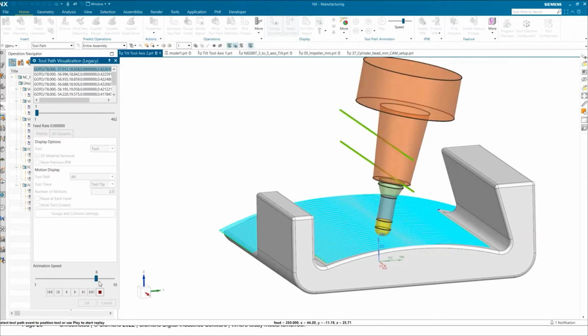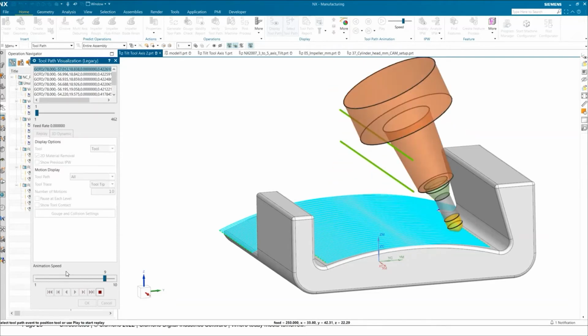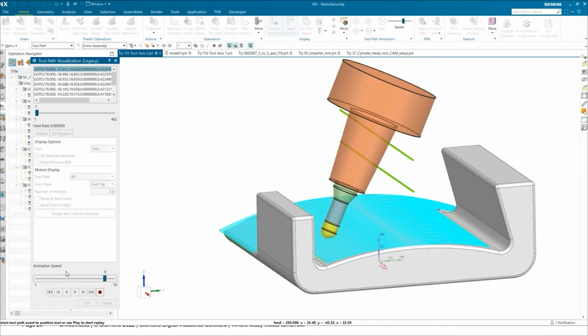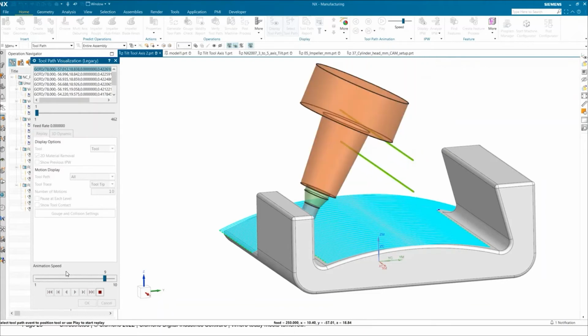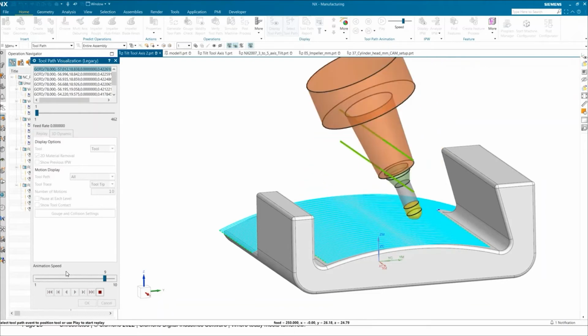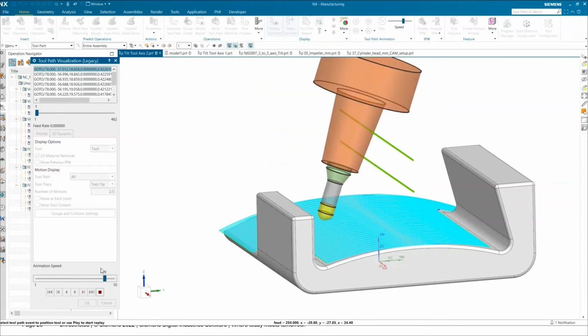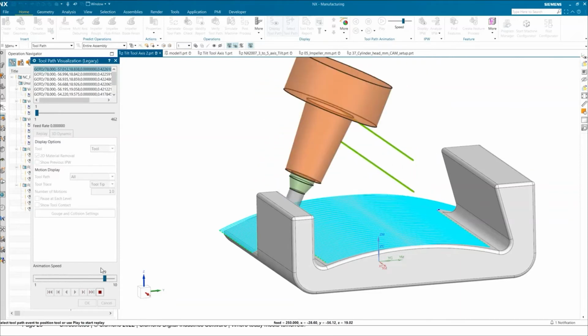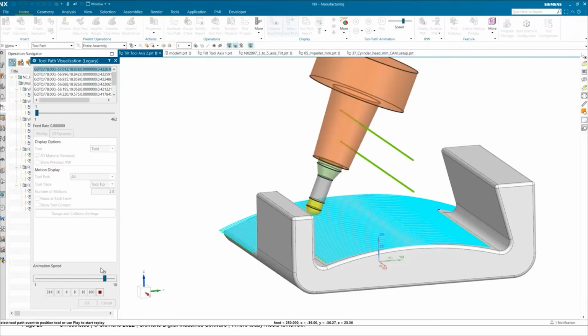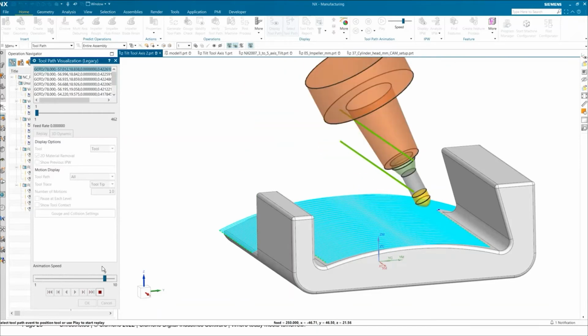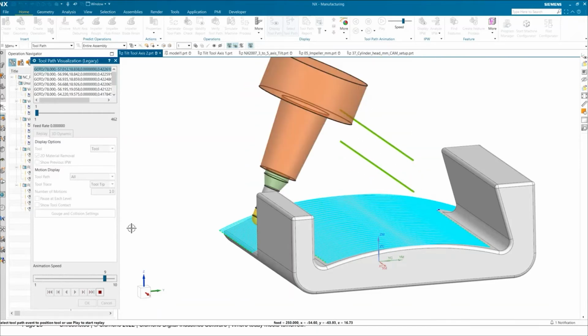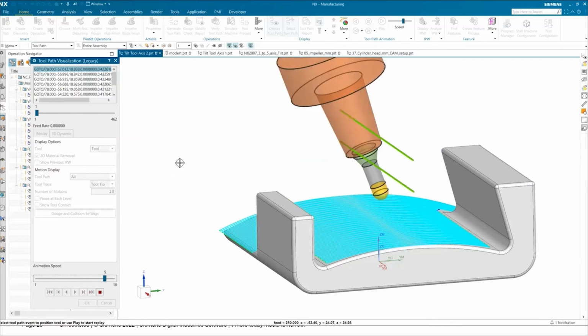And that was fairly simple. The idea is that if you don't know how to do 5-axis, trying to get an operation to do that fairly quickly might be a little bit difficult, but you can just create your 3-axis. Don't worry about the collisions, and then let the convert tool axis, tilt tool axis, convert it for you.